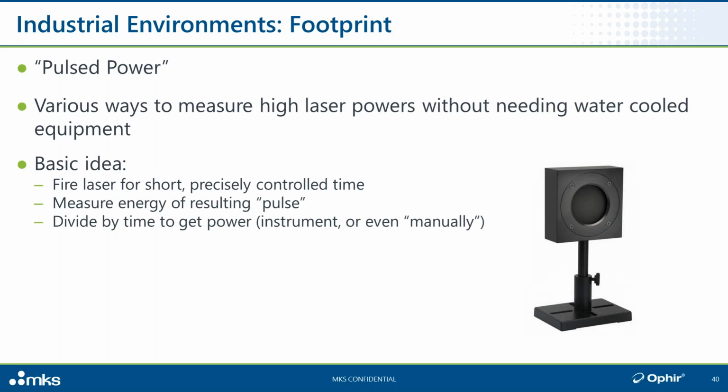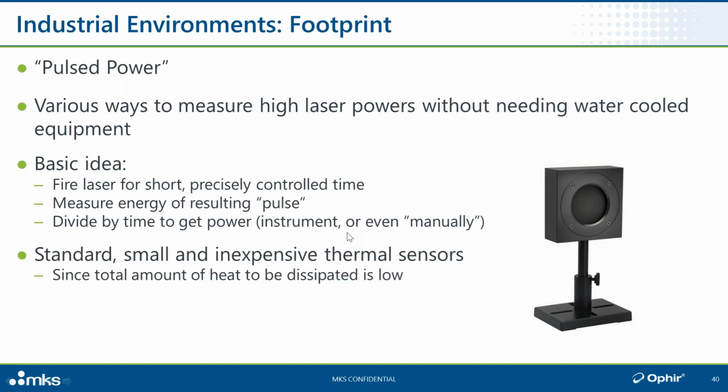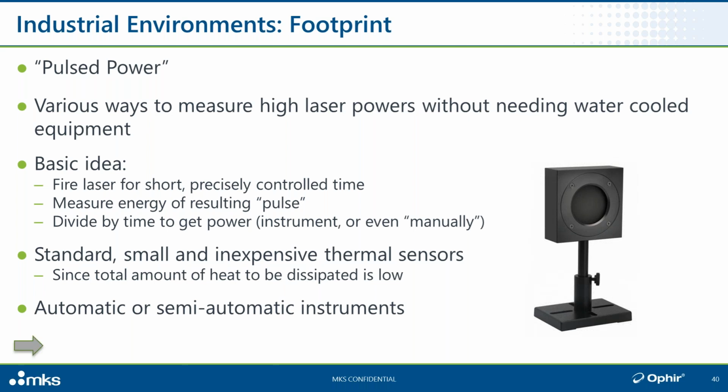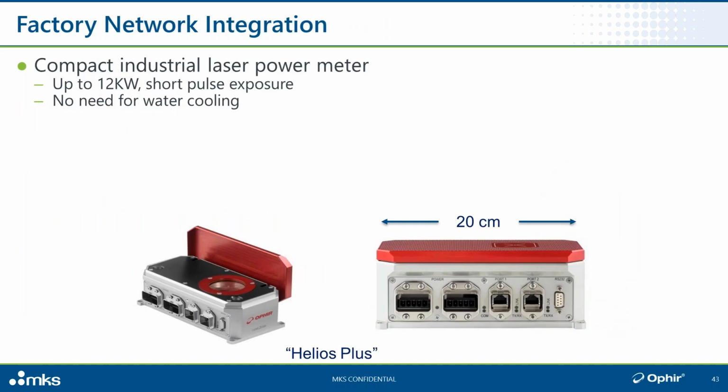Okay, so we have a bunch of regular moderate power sensors to which we gave particularly high energy scales for exactly this purpose. And that lets you use small moderate power sensors to measure very high power beams. Then you give them some time to cool off, because they're not able to withstand that power level continuously, but that's okay in this kind of mode. Let's look at some self-contained instruments that are completely standalone.